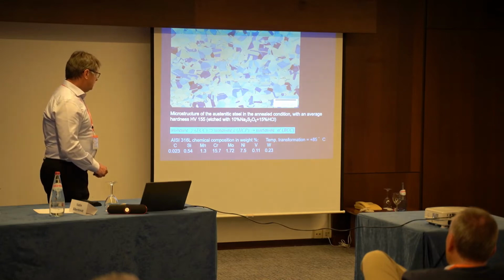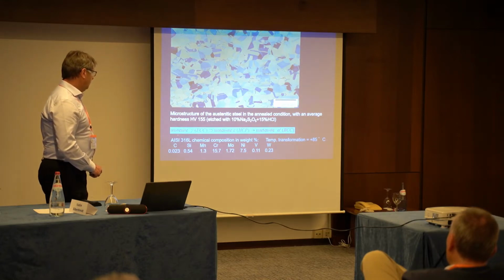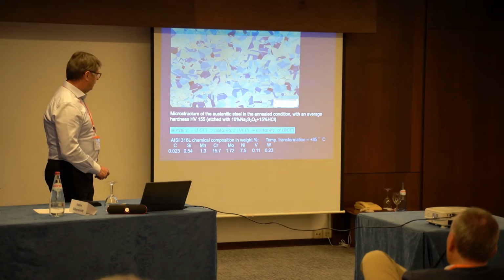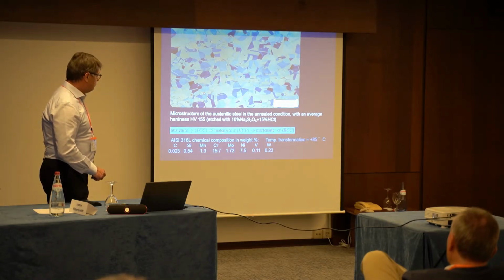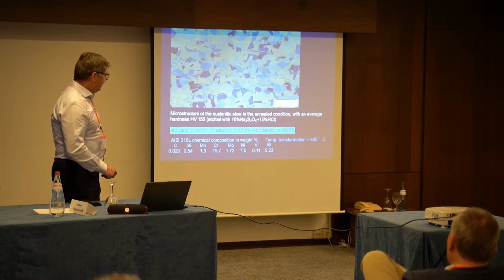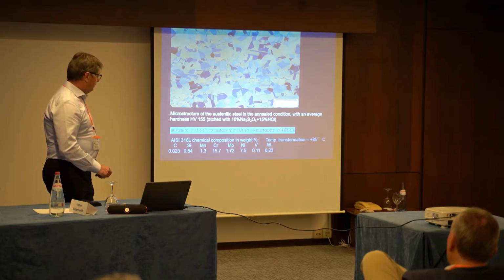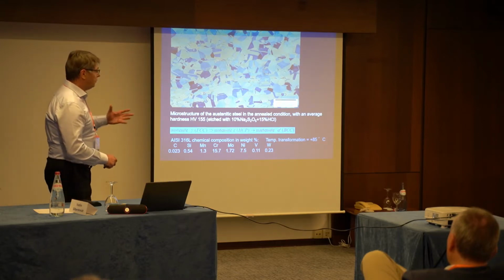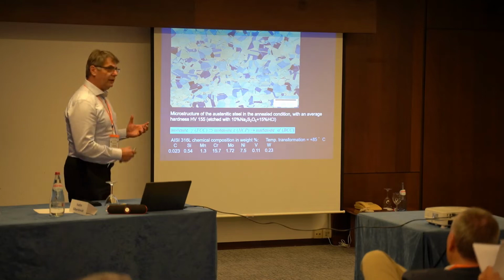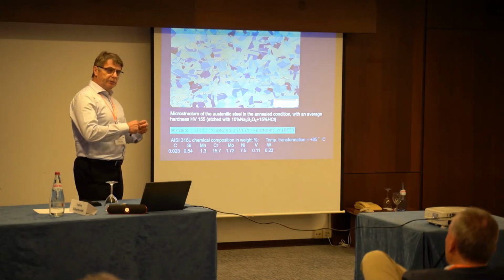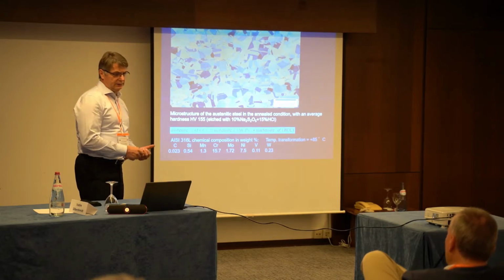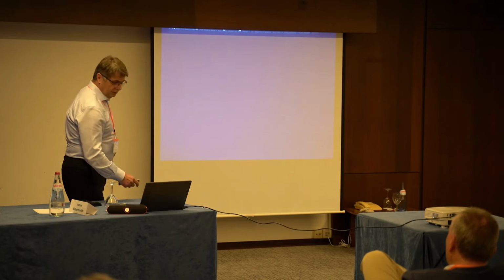The solution is typical: you have the austenite, gamma, which is a different crystal structure. Then you change to martensite epsilon, and later you have the stabilized martensite alpha prime. This is how the process works. But you know that with transformation to martensite you get a bigger volume, and with bigger volume you introduce additional stresses in this material. This is the point.